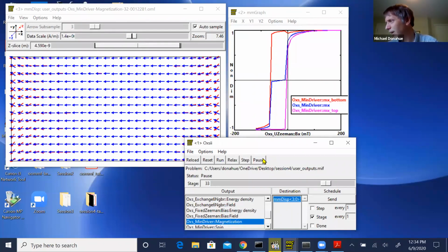All right. Any questions? Okay, so let me answer a few questions here. How do we determine which RK method to choose in general? If you don't specify the Runge-Kutta method, you get the default, and if you look at the documentation, it tells you what paper these came from. It's a good compromise between accuracy and stability. Most of the time it works well. Just use that one unless it goes unstable. If the simulation goes unstable, which you can tell because it just goes nuts, try using the RKF54S because it's a little bit more stable.